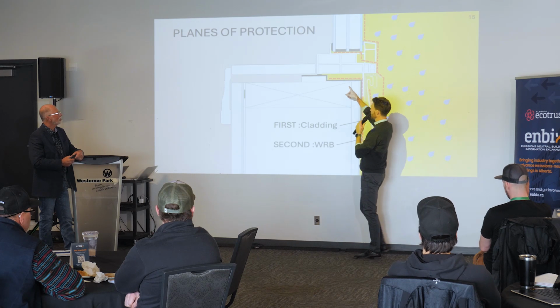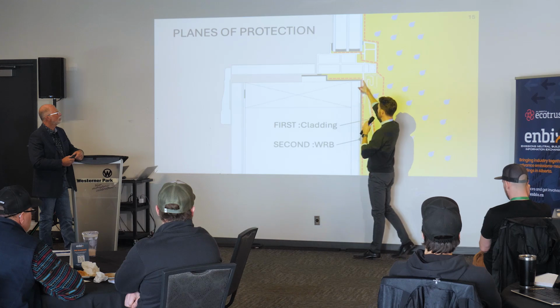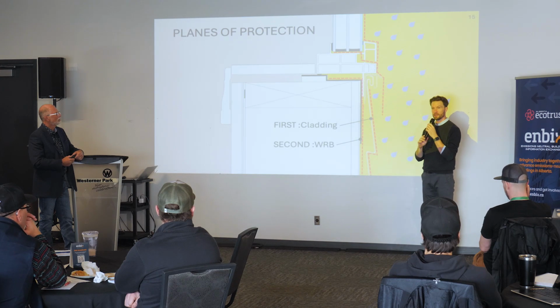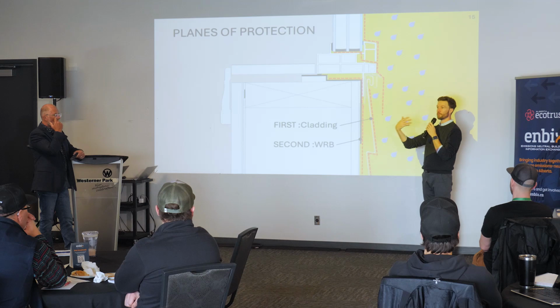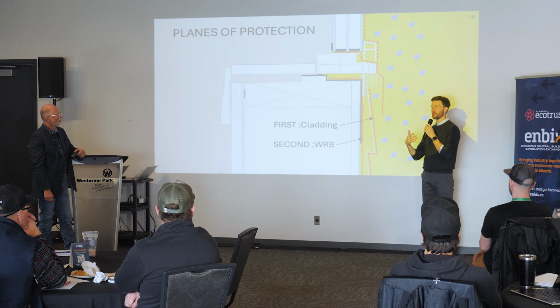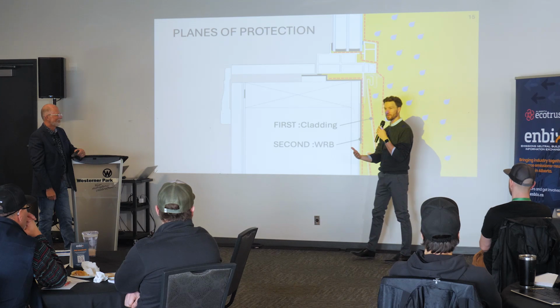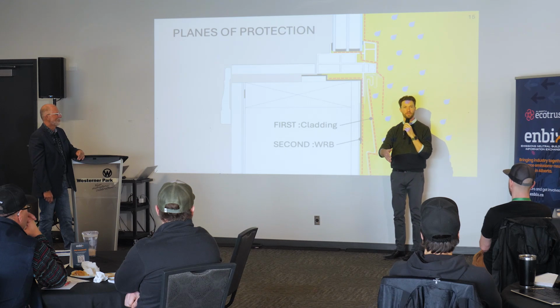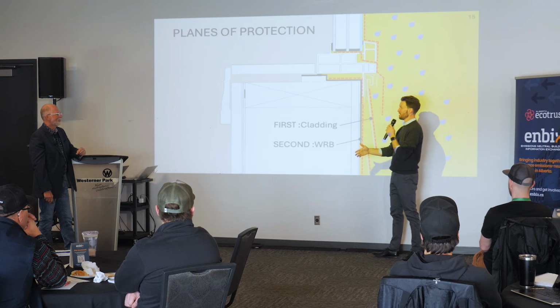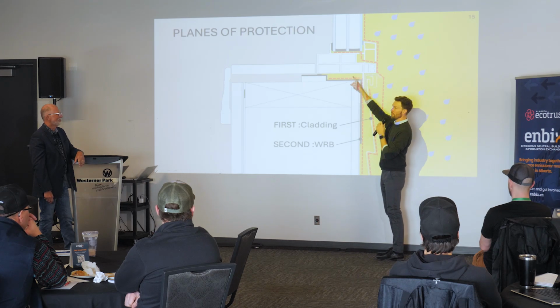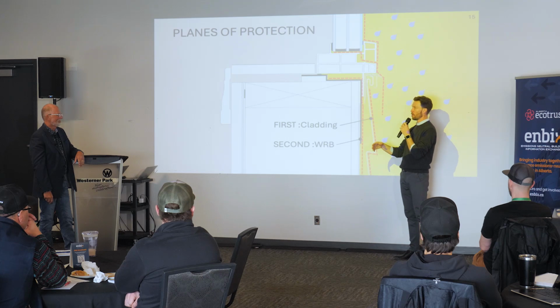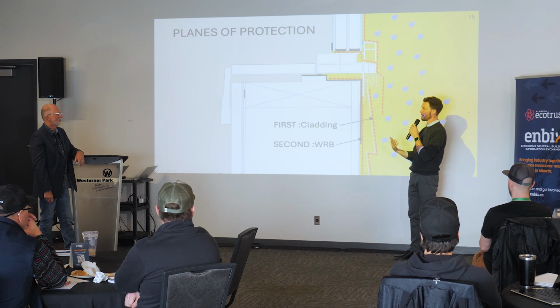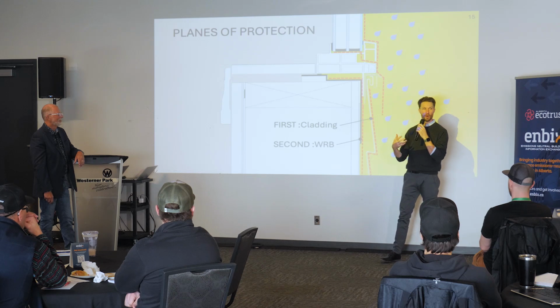But I love this slide for a couple of reasons. Number one, pointing out that this bottom flange is a location for the release of water. Sometimes it comes up against well-meaning junior tradespeople that get told, you go seal the windows, here's a roll of tape. And how many sides do they think they should seal? All of them, right? You seal across that, and all this great work you've done, now you've got a holding tank for water instead of a way to let it out. So you've got to monitor that sort of thing.